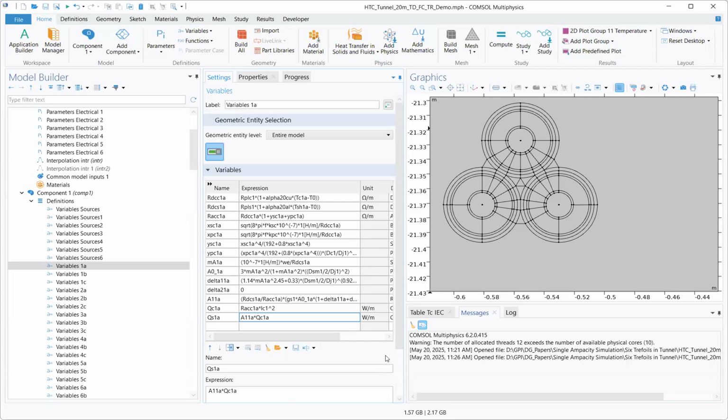The IEC standard 60287 series gives you equations to compute the heat sources and the ampacity of the whole thing, considering all inductances, all mutual heating, all eddy currents within a circuit. There are no eddy currents from one circuit to the other in the ampacity standard calculations.